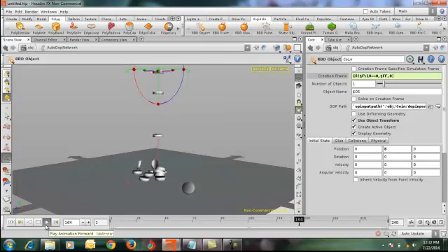So right now, at a multiple of 10 frames, at 240 frames I've got 24 coins. If you want to increase this, you can always increase the number of coins falling onto your scene. Just change this from multiple of 10 to multiple of 5. It will double, right? So let's rewind this and play. Now I am getting a coin falling every 5 frames.